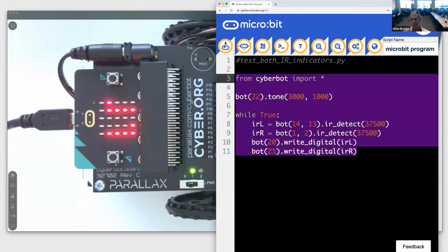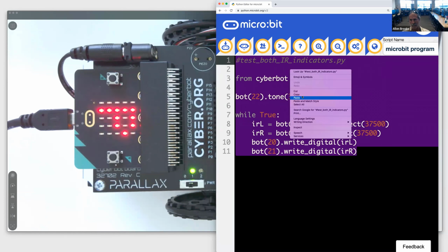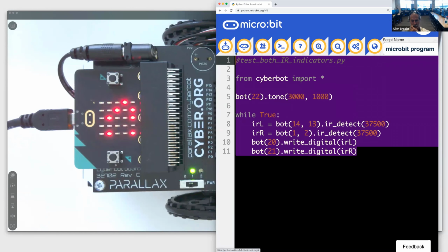Okay. Thank you. I'm just unfamiliar with reading. Well, there's more to this. I didn't get a chance to look it up because there are 2 versions of reading. One changes the direction of the pin to input before it reads. The other just reads but leaves it alone. So you can actually read whether or not some other part of your program is sending a high or a low. I don't know if I included that one or not.